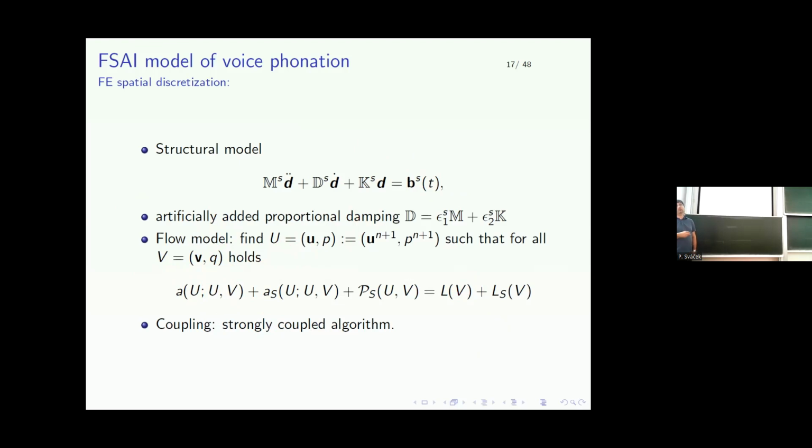But for the case of a high Reynolds number, which is the case here, we need to overcome the dominant convection, which results in the need to add a stabilization term. Here we use two stabilization terms. The first one stabilizes the momentum equation, but it somehow increases the weight of the momentum equations in the whole system. So the second term is an additional stabilization of the divergence equation, which means that because the divergence of u, the velocity, should be equal to 0, it's only written on the left-hand side.